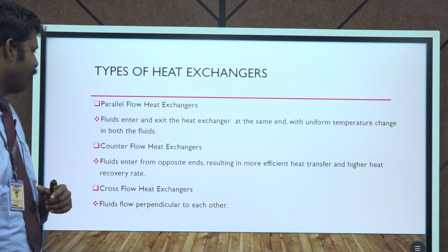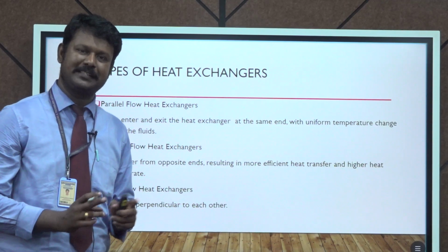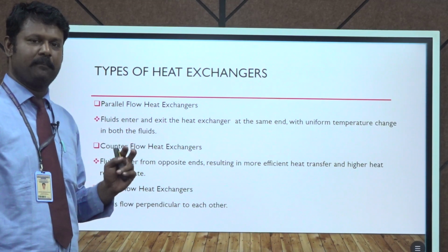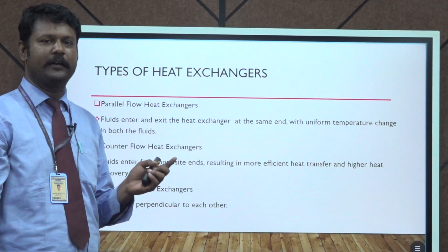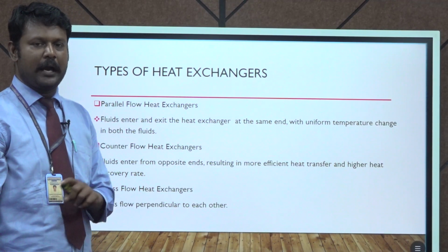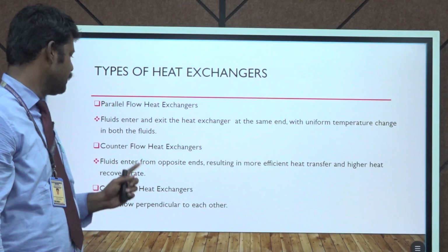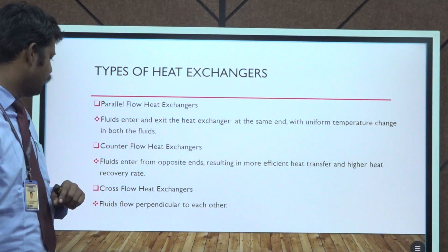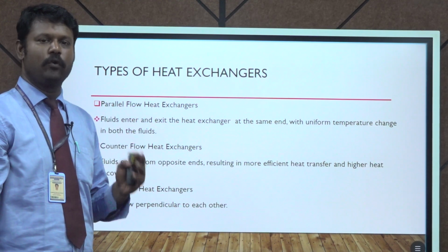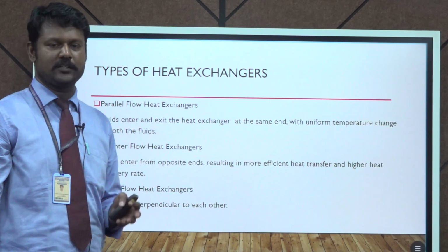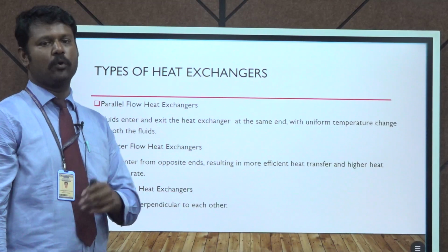What is a counter flow heat exchanger? When the hot fluid and the cold fluid have opposite ends, that is, the hot fluid enters through end number 1 but the cold fluid enters through end number 2, and both fluids are unmixed and travel in opposite directions, that is known as a counter flow heat exchanger. Cross flow heat exchanger: in a cross flow heat exchanger, the flows are perpendicular to each other, that is, the hot fluid flows perpendicular to the cold fluid.